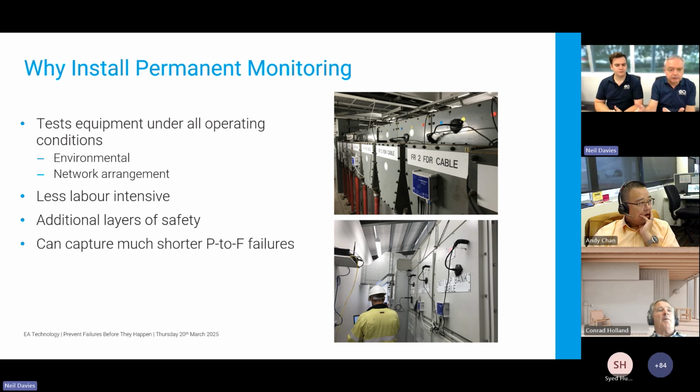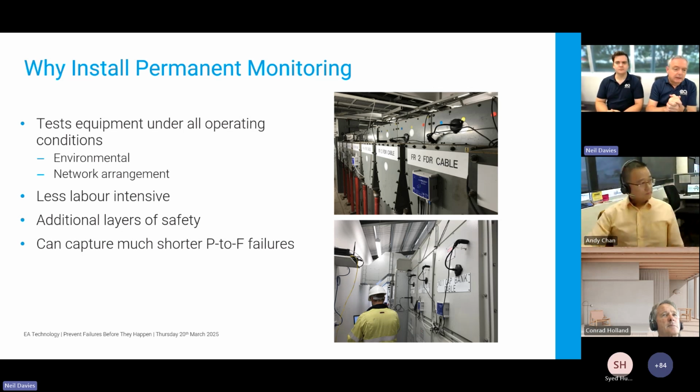So on the fixed portion of the switchgear, if you like, on rackable switchgear in the CTs or the cable termination, there's a discharge. If we just go by the first test using a handheld on the day when the circuit breaker was closed, then we can potentially miss that. If we're not going back for another year, then that could be a discharge that we missed.